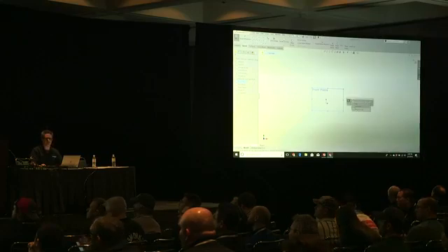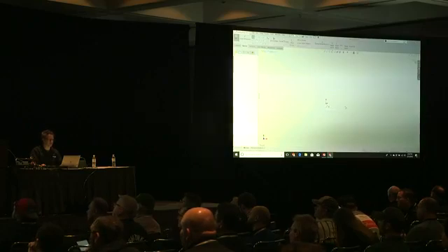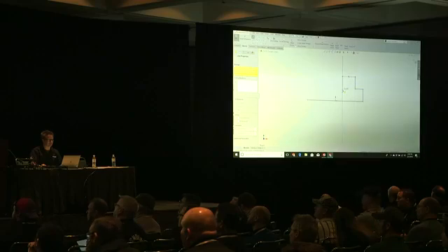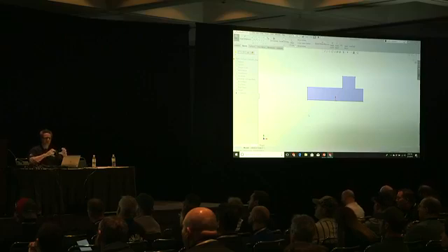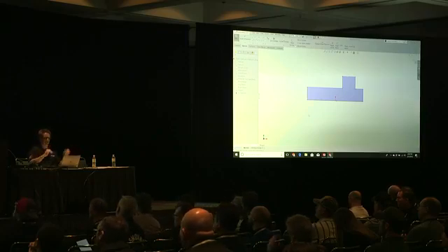Midpoint line. Anybody using midpoint line? You want to use this, and I'll show you why. Midpoint line, it goes straight to a regular line. And one of the things, I used to work for a VAR a long time ago, and I tried to impress upon people to sketch sloppy. You want to be in the ballpark, you want to be close, but don't get hung up on it. Just watch for the clues. You know, I want vertical, I want these aligned, I want to assume these relations.